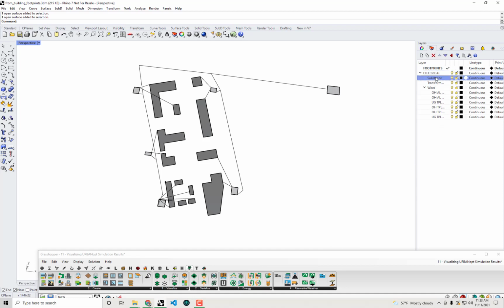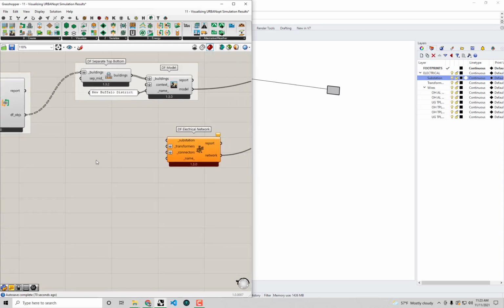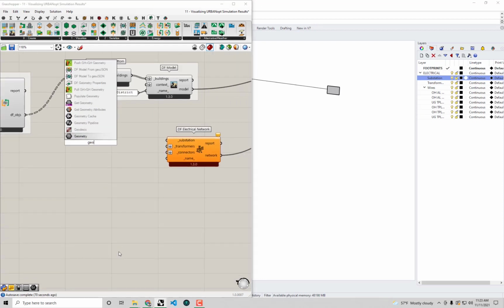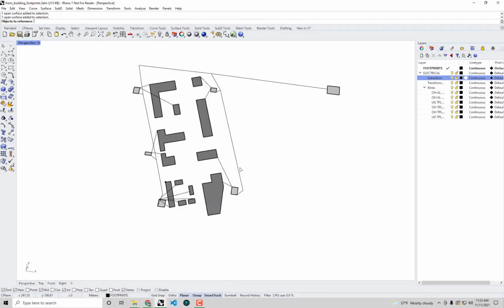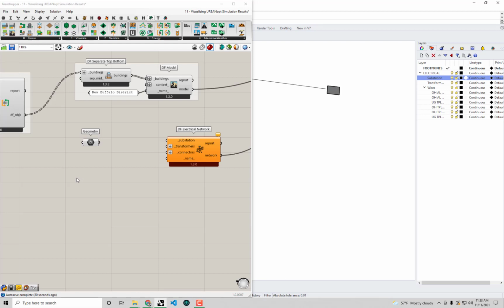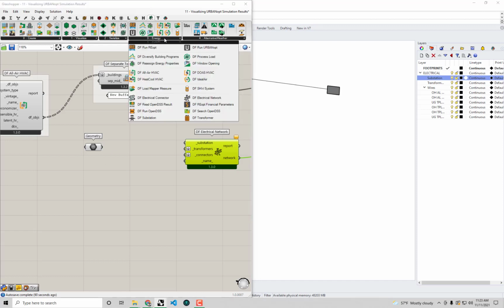You'll see first and foremost we have a single geometry for the substation. I'm turning that on and off here, right? This is our substation. So I'm going to bring this geometry into Grasshopper just by double clicking and typing, bringing up a native Grasshopper geometry parameter. I'm going to say set one geometry and just select our singular substation. And in order to make sure that it has the properties of a substation, we have to pass this geometry through a component.